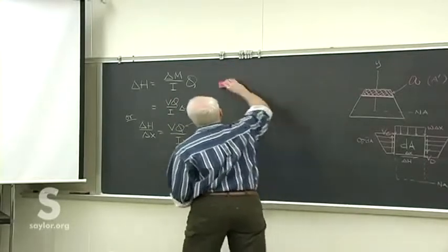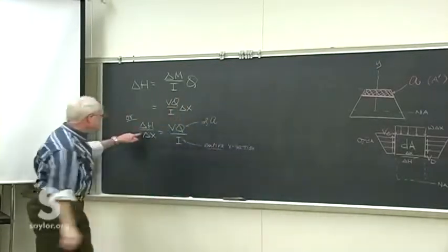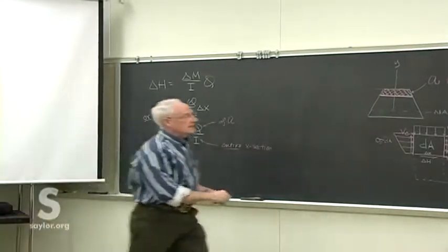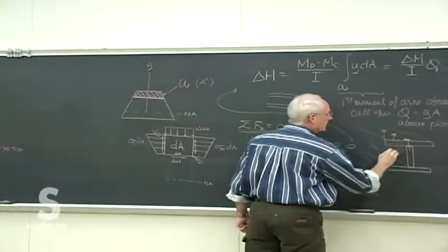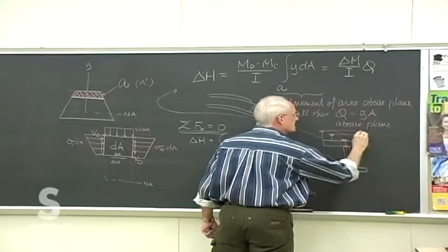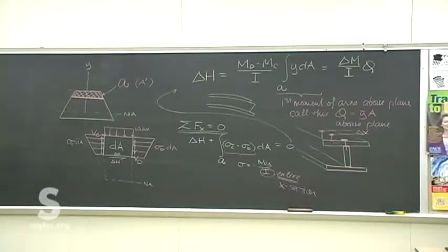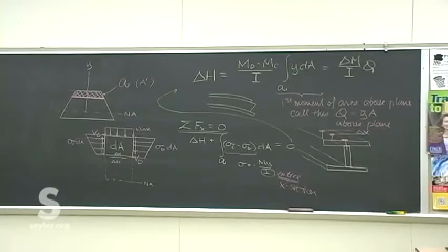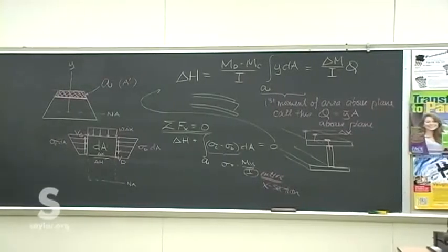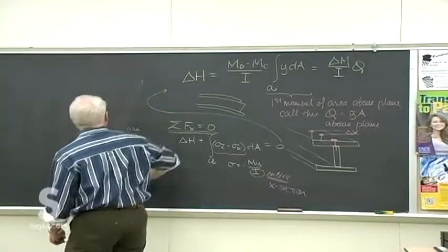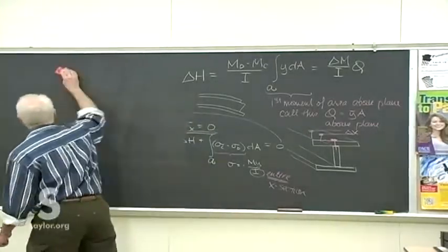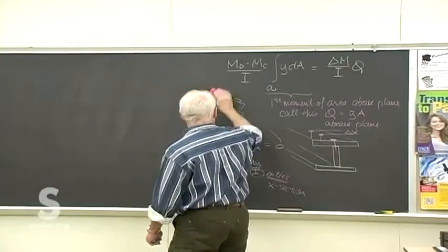So now we can determine what the shear is per unit length. The way we'd use that is if you were going to nail these, you'd put nails every couple inches, and it's easy to use that as our distance delta x. So we can figure out how much shear there's going to be per nail, and then we can make sure we got nails with enough thickness and area that they can withstand that. So we'll do that very problem as an illustrative example of how we work with this.